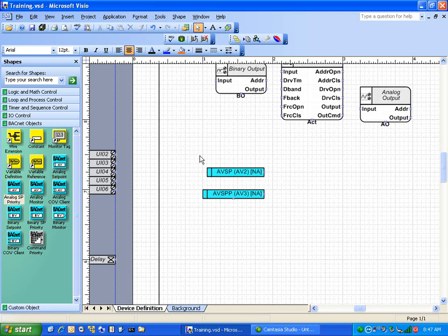If you need to pass down anything that needs to be automatic, maybe you're sharing a space sensor from another controller, maybe you're passing down the outside air sensor, I recommend using the analog set points. They don't have a priority array for writing, they just have one straight input, and what you link to it passes down to the controller. And it's less resources, it's less memory hoggish.